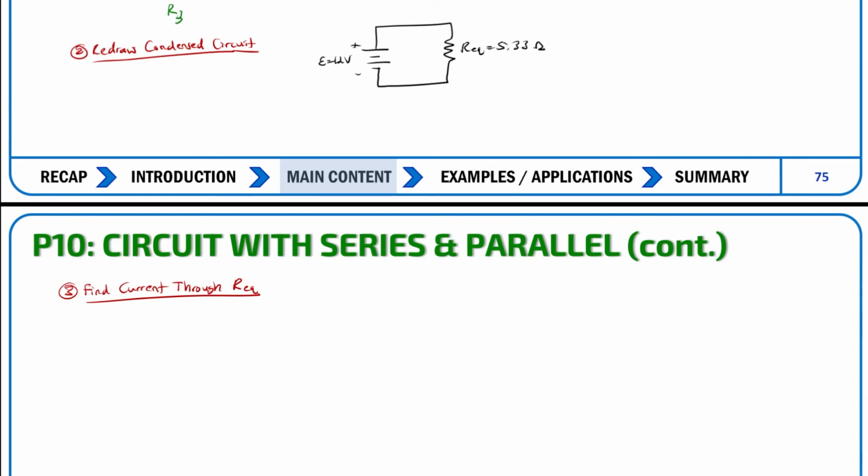Now the current through Req is going to be constant, so V equals IR. We know I is going to be equal to V over R equivalent. So that means we have 12 volts being distributed through 5.33 ohms of resistance, and that's going to be 2.25 amps.